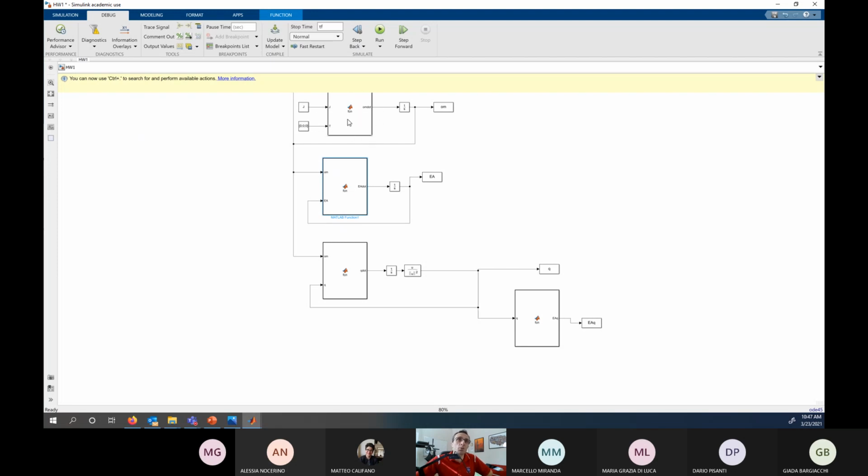So if I didn't have Euler's equations, and these are the equations of motion that give me an explanation of why omega is changing the way it is, and the why is, in this case, the distribution of mass J, and the torque that is coming in, in this case a bunch of zeros, but it could be something else. So that's kinetics, and that allows me to generate the angular velocity behavior that feeds the kinematics. So from the point of view of what's causing the motion, this block doesn't care. This block, the Euler angle block, only needs to know what omega is doing. As long as you feed it omega, no matter why it's behaving that way, it will be able to tell you the time history of the Euler angles. Okay?